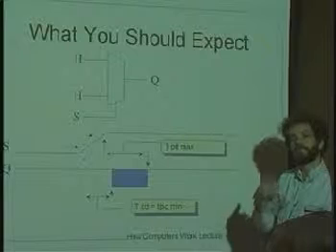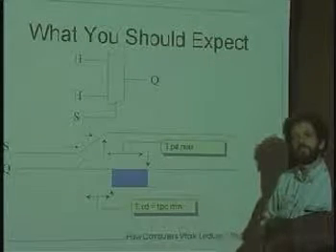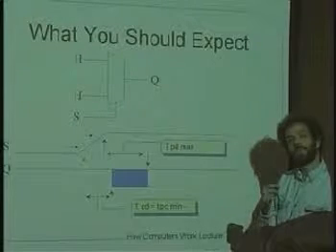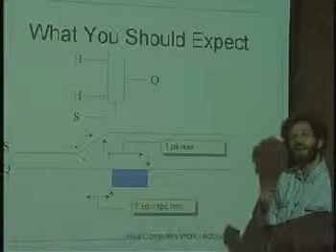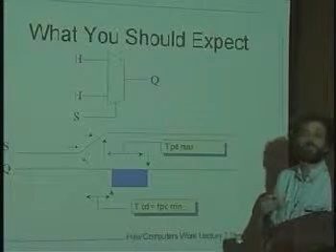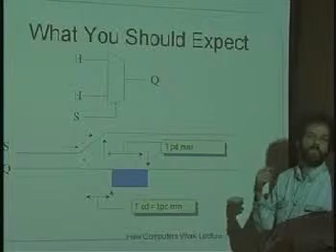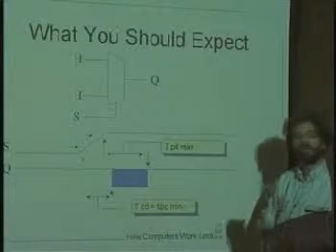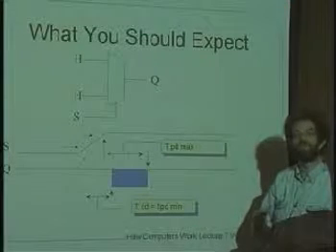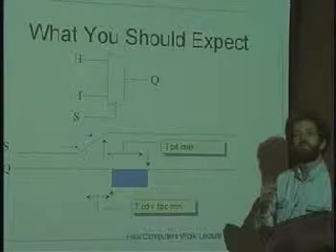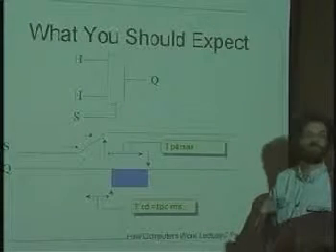What we care about mostly is how quickly will we lose the old data going around the loop. Whereas with propagation, remember how that was used. That was used to figure out how soon can I clock the circuit again and make use of the output. And there the question is, over the entire temperature range, over all kinds of different parts, things like that, over different data, what's the longest that it could take for the new valid value to get there so that I know when to wait until I clock it the next time. So that's why that's in general measured in terms of the maximum.